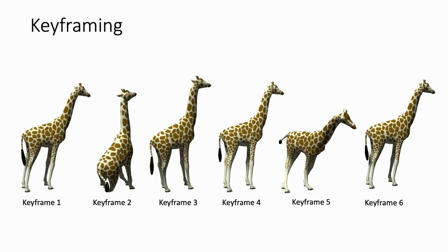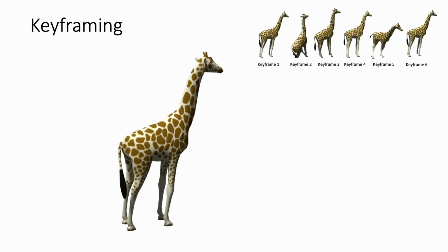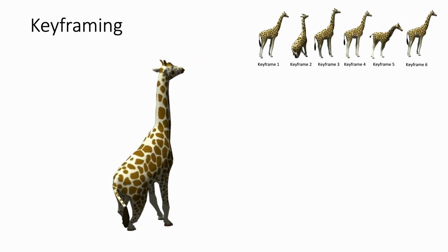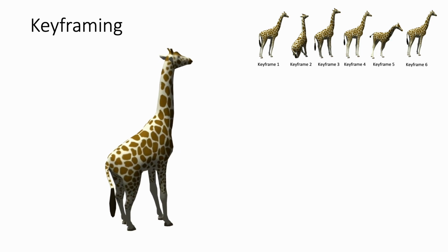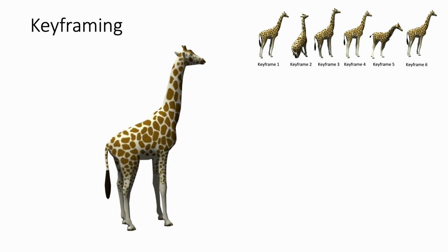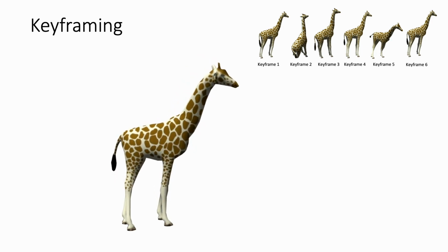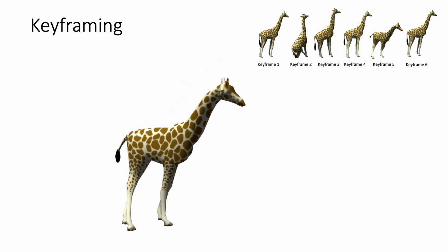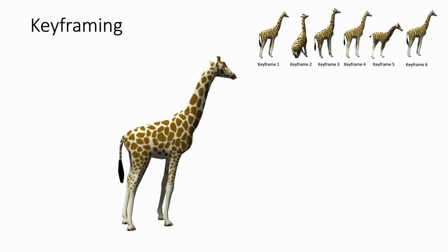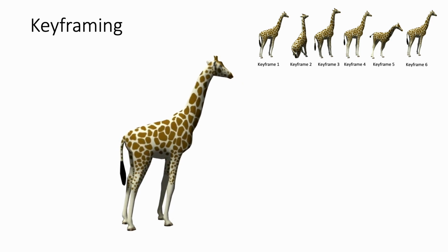In addition to subspace simulation, our method can also be used for keyframe animation. We create 6 keyframe poses of the giraffe model by interactively exploring latent space. Based on these keyframe poses, we generate in-between trajectories with physically plausible deformations by means of interpolation. While linear subspaces typically require nonlinear interpolation schemes to achieve acceptable results, our nonlinear subspaces produce physically plausible deformations even for simple linear interpolation of modal coordinates.